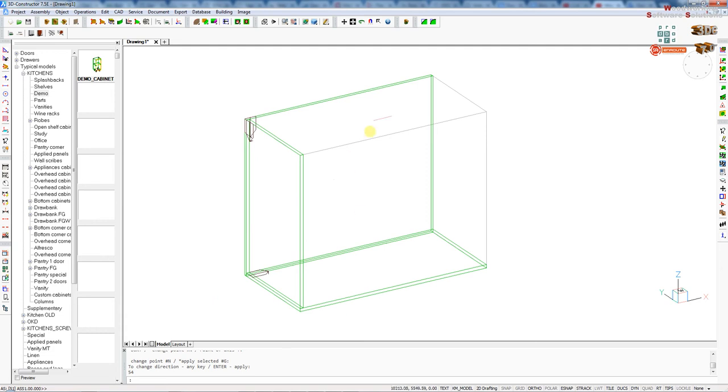We can use this function to build another vertical, but we can also copy the existing vertical part. So we can select copy, and we can copy this part. So we create this new part. We need to relocate this part because we want to have it exactly in position. There is an operation called reference. You'll click on this reference to the coordinate system of the object.